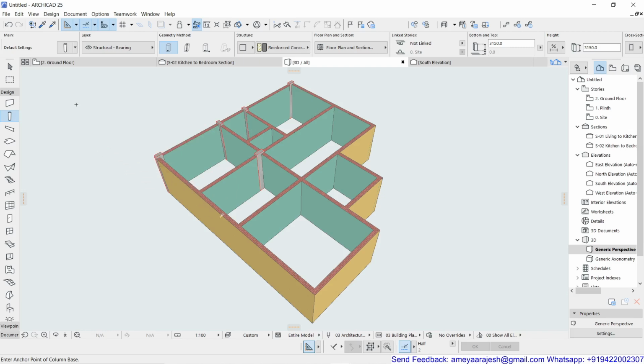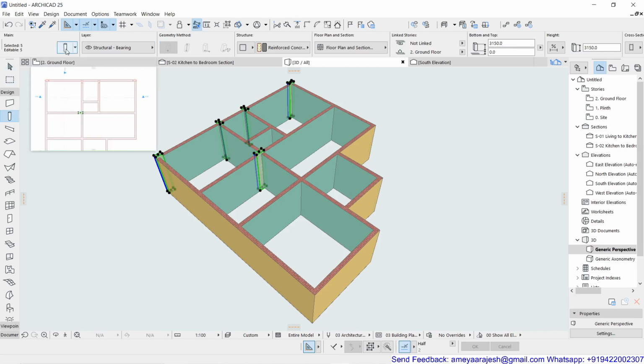So this same tool I should select, right? So I have selected my column tool default setting, that is in draw mode, and then I'm going to hit Control A from the keyboard. Control A, select all, but what is matching my currently selected tool. So I have selected the column tool right now, so all the columns which I have inserted in my project are automatically selected.